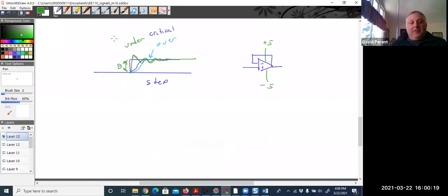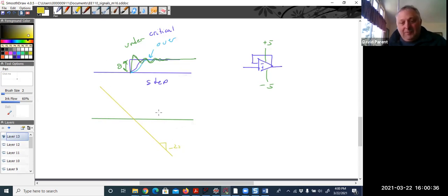So if something is finite and has no frequency response, it's flat. So wherever it's flat. If something is acting like an ideal integrator, it's a line with a minus 20 dB per decade slope. And if it's acting like some kind of low pass filter, first order would be here.